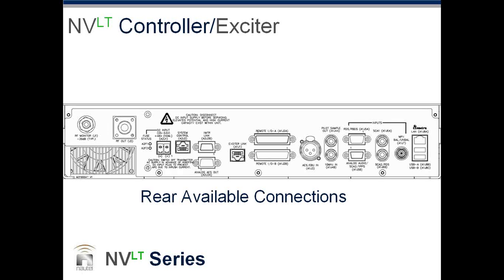Go ahead. Yeah, I was going to say, the next connection, this exciter, unlike our previous exciters, actually runs off 48 volts. Yep. For redundancy and for ease of DC distribution and such, we thought it best to run the exciter off of 48 volts. You have multiple power supplies in there that are providing 48 volts. And so in the old days, when you had an AC feed directly to the exciter, if the power supply in the exciter failed, you're off the air. Right. In this one, I can have a power supply fail, and I'm still on the air. Right. You can have main and standby power supplies for that operation part of the transmitter.